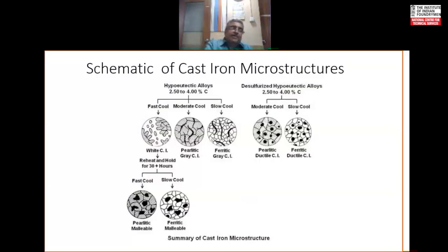Now, during the heat treatment, this cementite sort of breaks down. I'm using very crude terminology, and carbon diffuses out and agglomerates in the form of these graphite shapes here. Do it for long enough time, slow cool, and much of the carbon will come out, leaving behind a ferritic matrix. That gives you even bigger elongation than what you will get with pearlite.